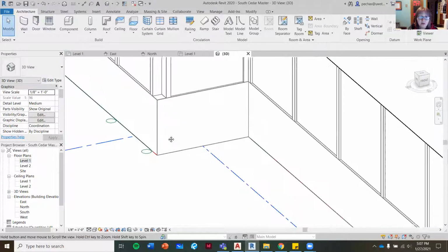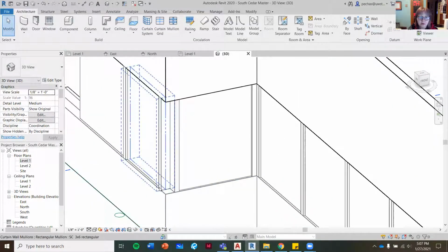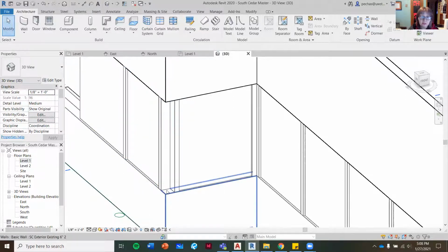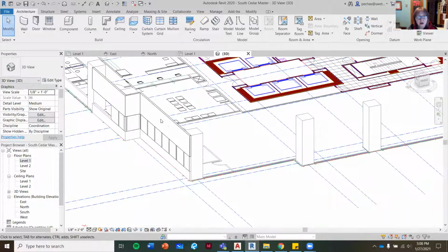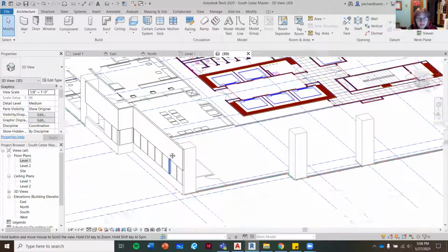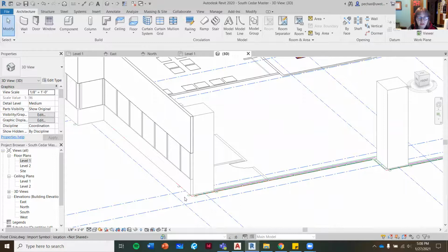We can talk about putting other mullions right here, basically just measure that area, make a mullion just the way we did before, use a square mullion as a base, and then you would just click on one side of it, click on the other side of it, and it'll just make a mullion. I can do a tutorial about that if you're interested in that. So that is making the curtain wall.